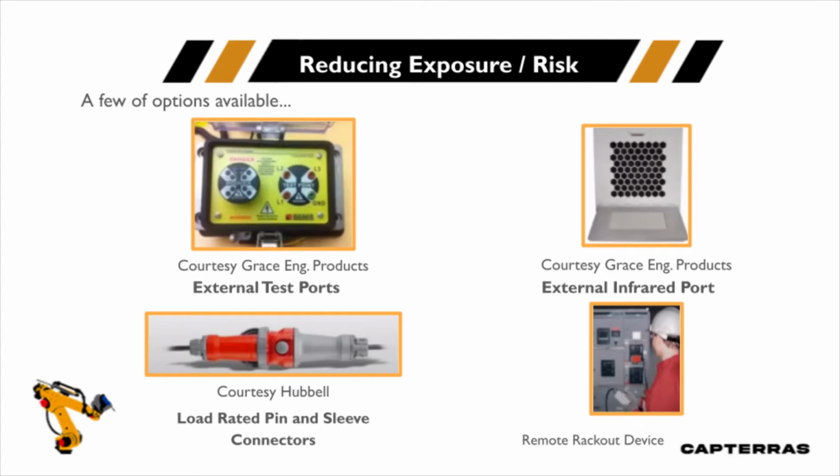Now, of course, if we have voltage at the top of the breaker, anytime we shut off the breaker switch, if there's voltage still at the top, the PPE still stays on if you're going to be within the shock or arc flash boundaries. On the lower left, we see a load-rated pin and sleeve connector that could be used for disconnects. My recommendation would be to still shut off the load before you disconnect this, but these are load-rated just in case someone did disconnect it under load.